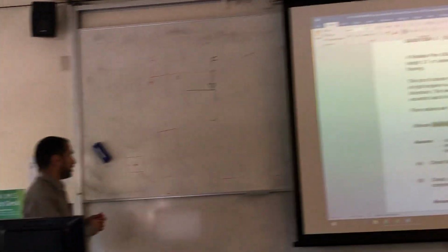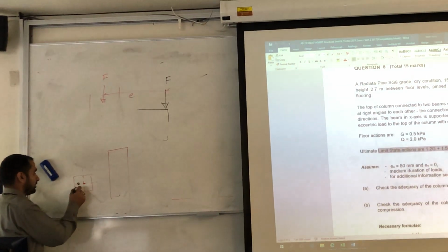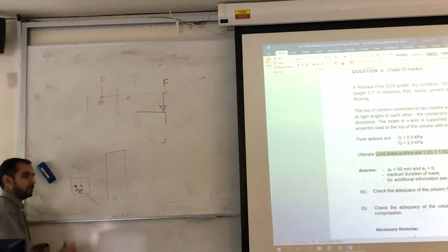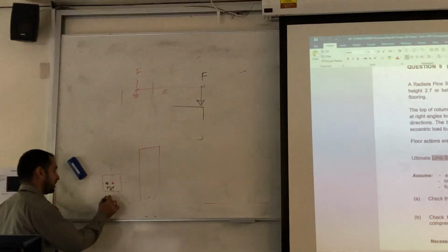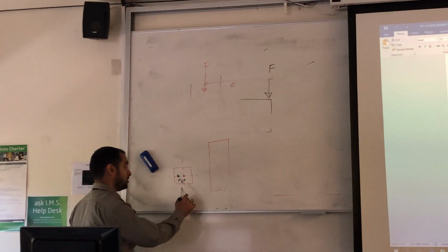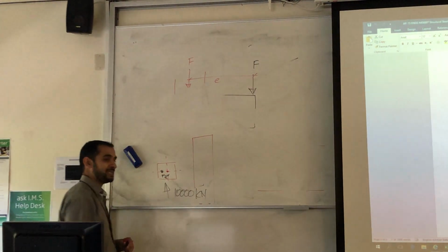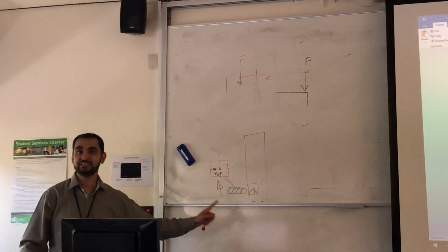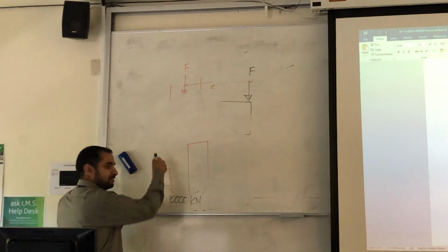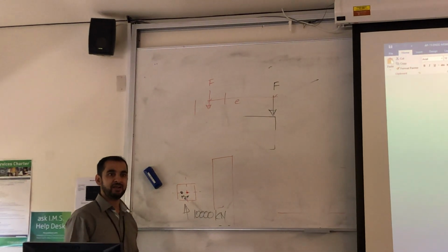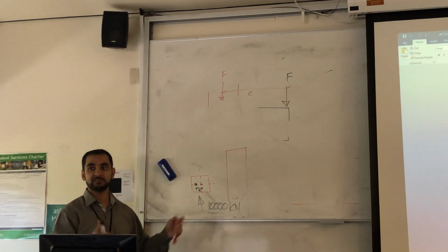But as soon as you offset those two things, the center of mass and center of rigidity, there becomes an eccentricity. Let's say you have an earthquake and big buildings, you have a 10,000 kilonewton force, even if it's 1 meter, what happens? 10,000 kilonewton meter of additional moment to be resisted by the lateral elements, right? So it makes a huge difference. Therefore, you will see this center of mass and center of rigidity a lot.